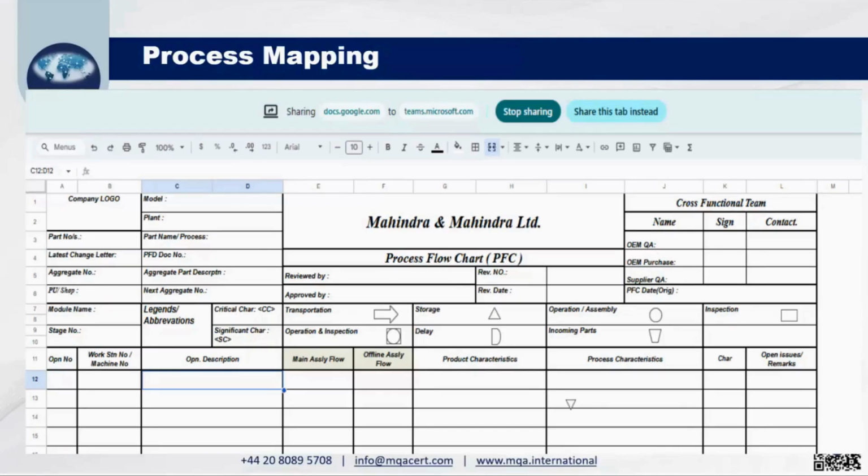So this is the company name, and we call it the process flow chart. We write the part number, process number, which plant is maintained, what is the model of this part, process flow number, what is the description of the part, at which stage of the shop floor it is made, and which is the next process. It is reviewed by someone, made by someone, approved by someone. There will be revisions. This is a live document, so it will have a document revision number and document revision date.